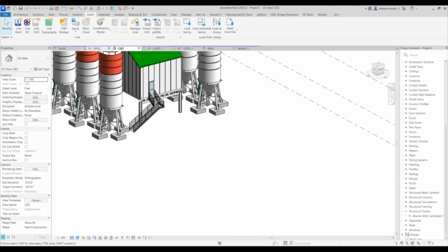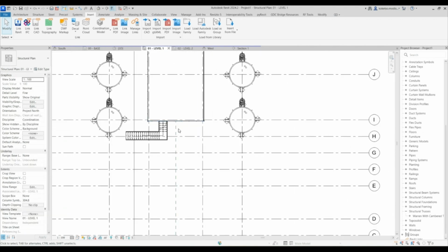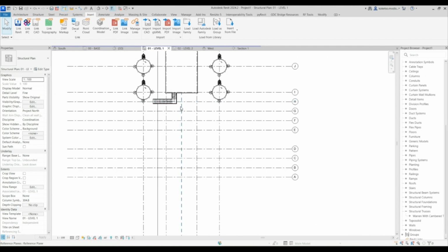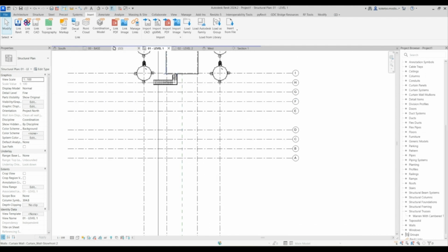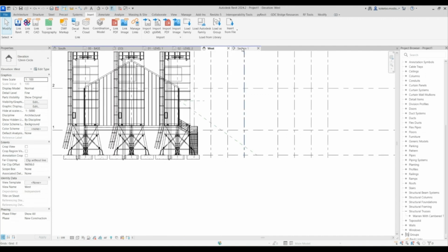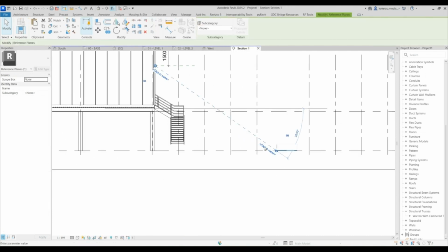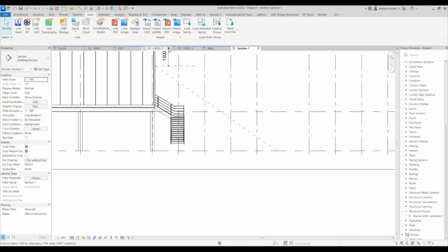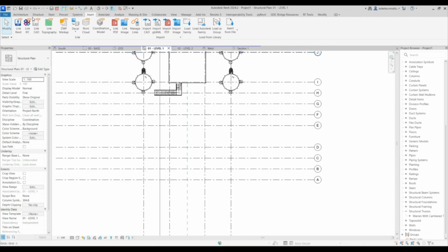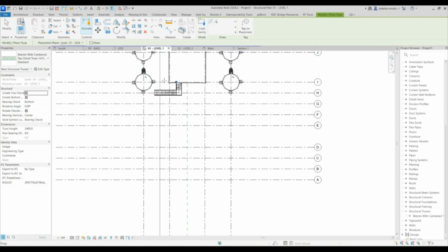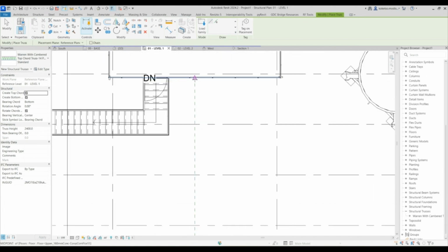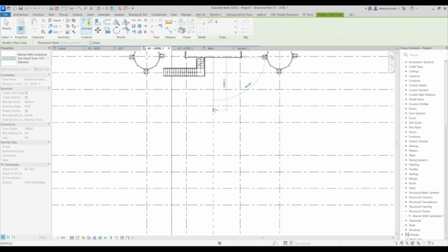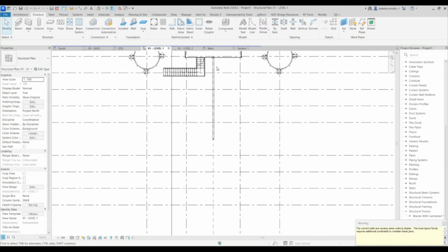And then I'm gonna go to, let's say, level one. I think level one is fine. So I'm gonna go back to my section one and rename this reference plane and name it conveyor. Enter. Go to level one, structure, truss, and then I'm gonna set my reference to reference plane conveyor, and then I'm gonna draw my structure from this point, and then towards that point, I'm gonna make it 10.5.